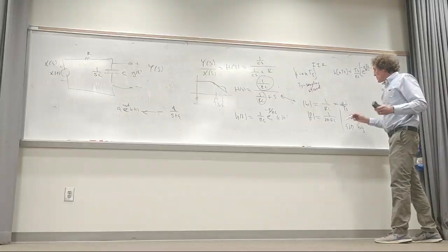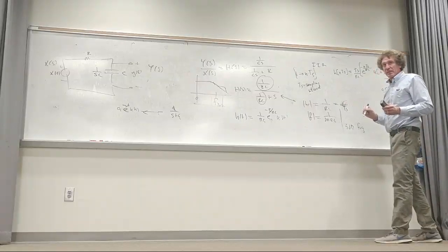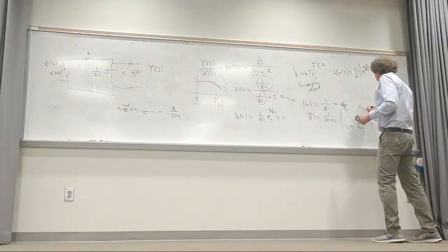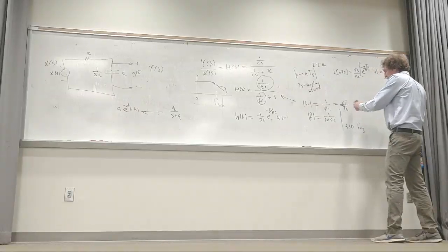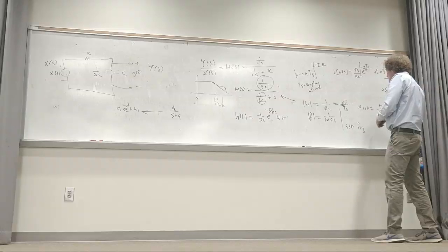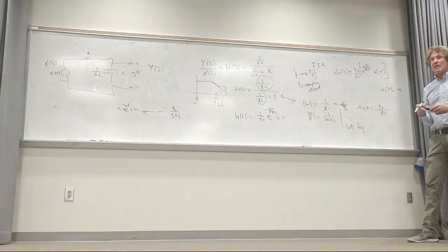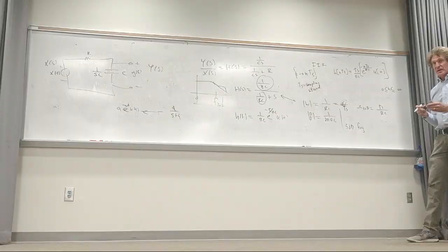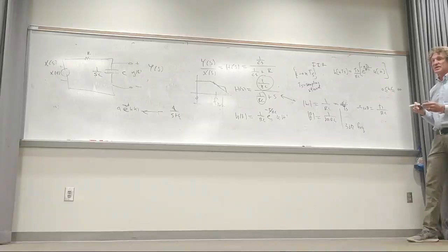So now the domain we're in is the capital omega domain. And that means the omega 3 dB, I don't expect you to know this by heart, but that would be simply TS over RC, and that would be for the capital omega domain. Follow me? Go ahead, Josh. Remember, small omega times TS is capital omega, where TS is the sampling interval.